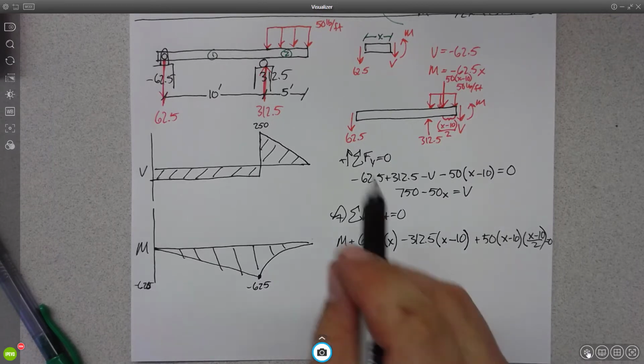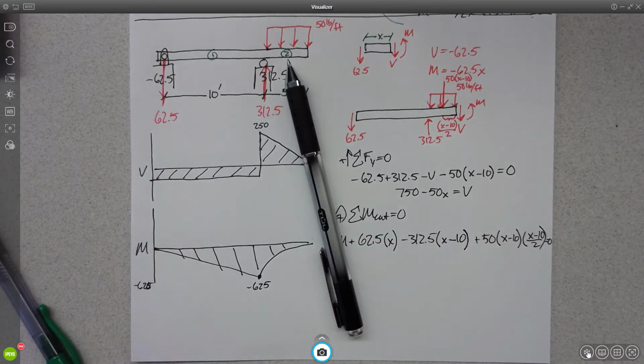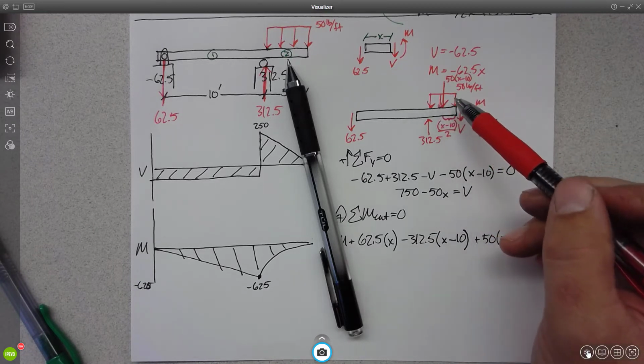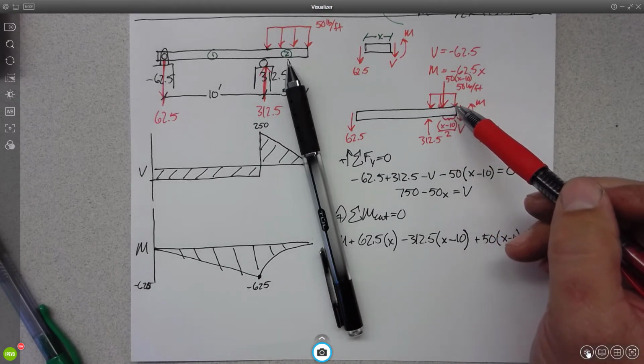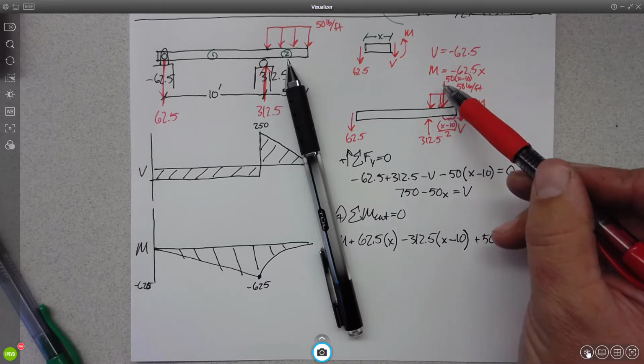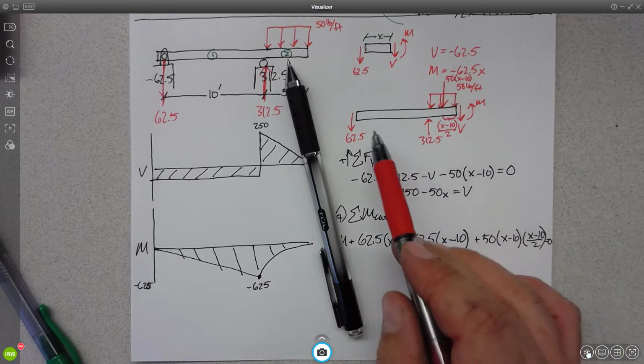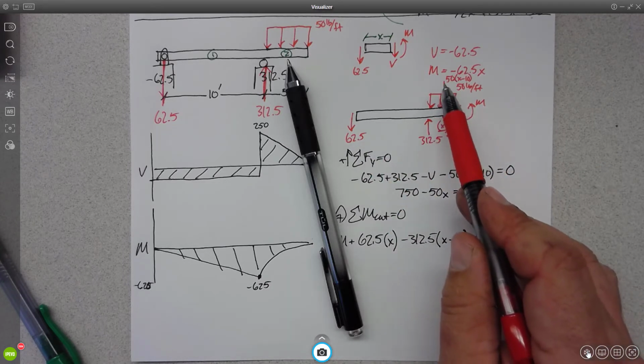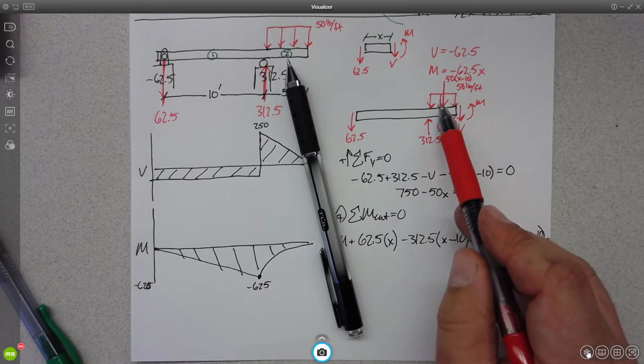Okay? So what are some tricks when you're working problems with distributed loads that you need to remember? Square distributed loads are divided by 2 for distance. It's going to be a curve. Okay. Parabola. Use the area between, like, how far down it goes. Okay, use the area. You just have to be really careful that even if we slice it mid-load like we've done here, that means there's a new resultant force that's going to be someplace in the distributed load.